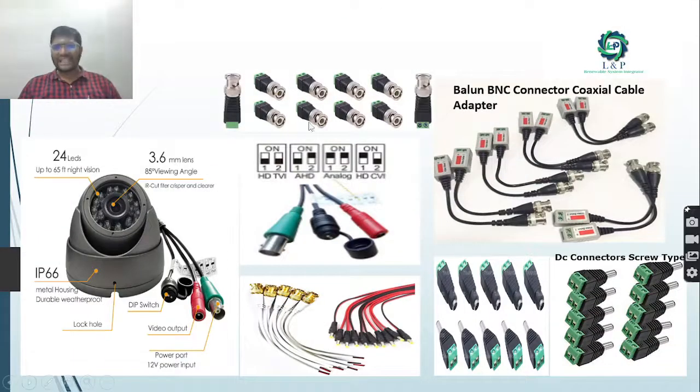There are so many connectors to connect to the BNC. See here, for the power supply, you can use these DC connectors, screw type connectors. We can have male and female connectors as well. Even for the BNC, we have terminal provisions like this, because it is very difficult to crimp such sort of things. So in such places you can go for these connectors, positive, negative. You need to connect in the concerned terminals properly, so the cables will work properly.